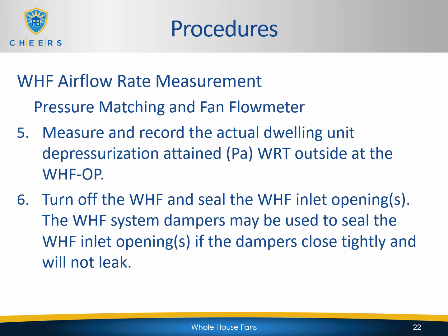Now you're going to turn off the whole house fans and seal the whole house fan inlet openings. The whole house fan system dampers may be used to seal the whole house fan inlet openings if those dampers close tightly and will not leak. Some of them will, some of them won't. If you're unsure, you can always close the damper and move on to the next step, and you're going to need to go back and check. If there's any air leaking through any of those whole house fans, then you're going to need to use another method to seal those off further so they don't leak.